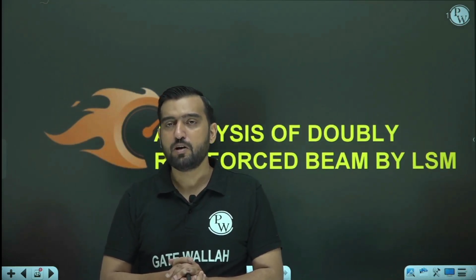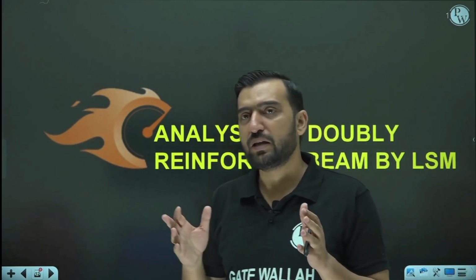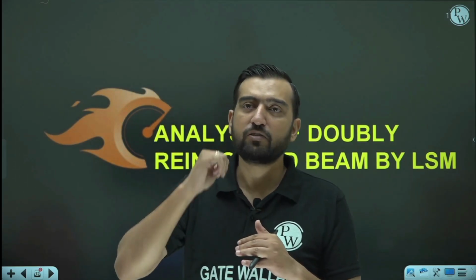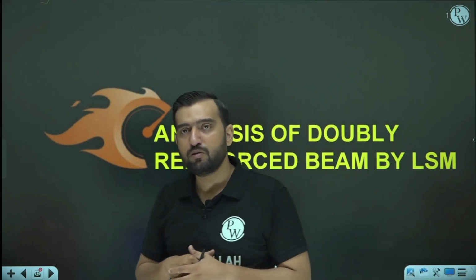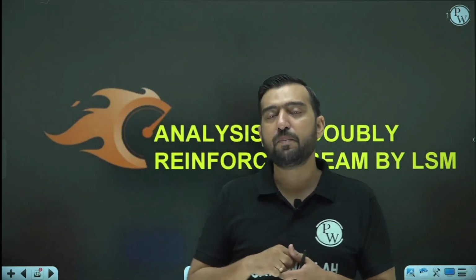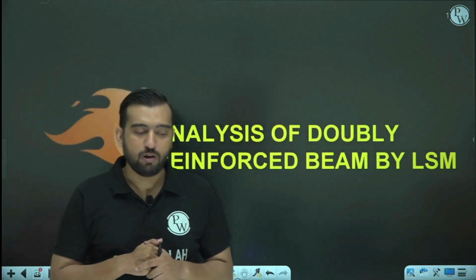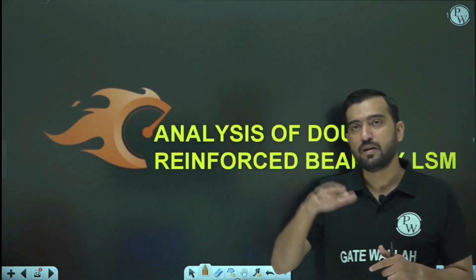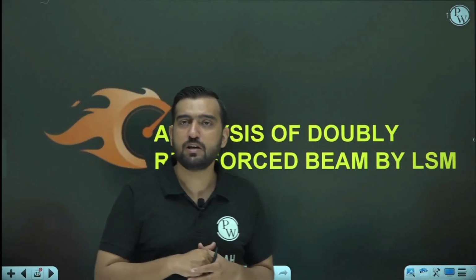Because by increasing the amount of steel on the tensile side, you may be increasing the tensile capacity of the beam. But you know that the tensile capacity of the beam has to match with the compressive capacity of the beam, and the compressive capacity of the beam depends upon the XU value, and you know XU cannot exceed XU limit. So there is some upper limit of compressive force. So with respect to steel, if that upper limit is on the lower side, then what we can do is increase the amount of steel on the compressive side.